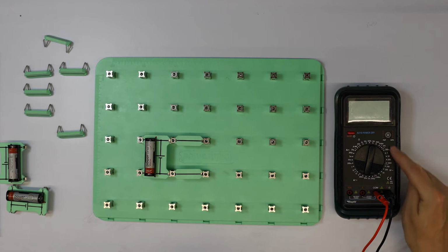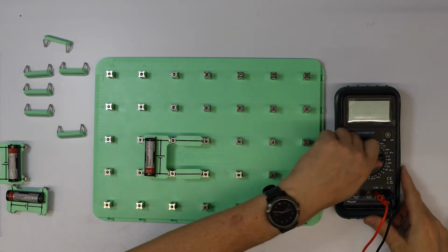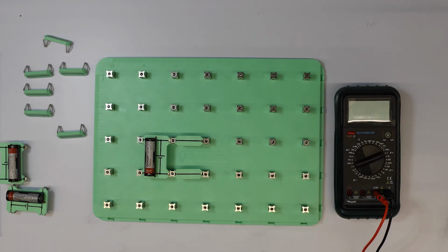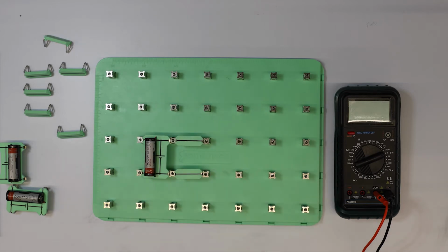And for each value, we've basically got a range, which sets the range of voltages or currents over which the meter is going to be sensitive. So if I change this here, I can set it on a 2 volt range for looking at the voltage across this battery, if I assume that it's going to be roughly 1.5 volts. So we know that that's going to fall within the range.